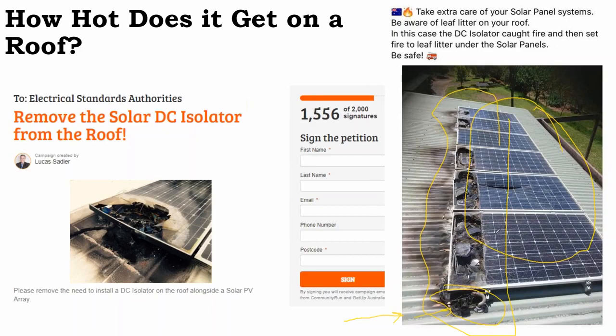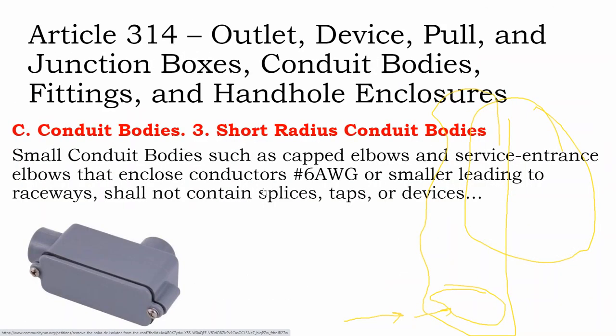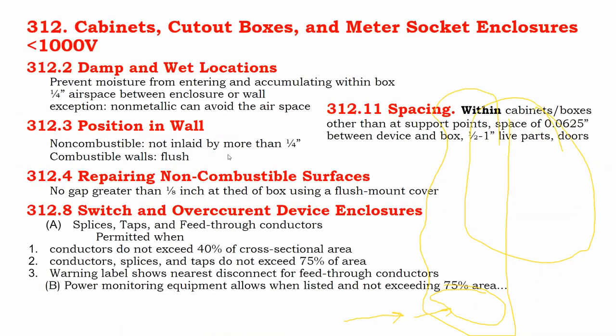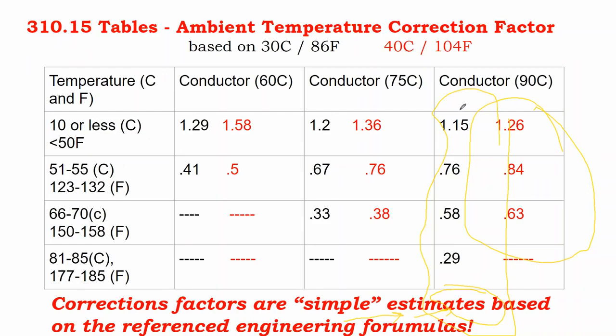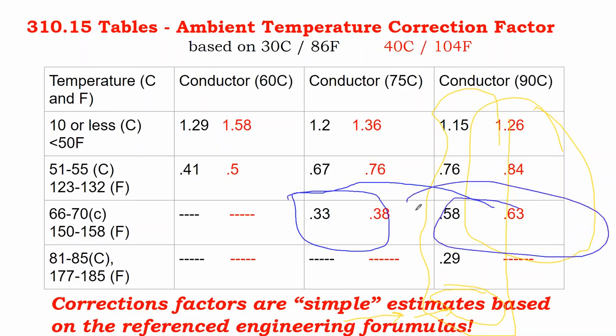And so if you've been doing all of your temperature calculations assuming a higher temperature rated device, and you go and swap it out with a lower temperature rated device, then we saw with those temperature correction factors that the temperature derating for lower temperature devices is substantially larger, 70% instead of 40%.